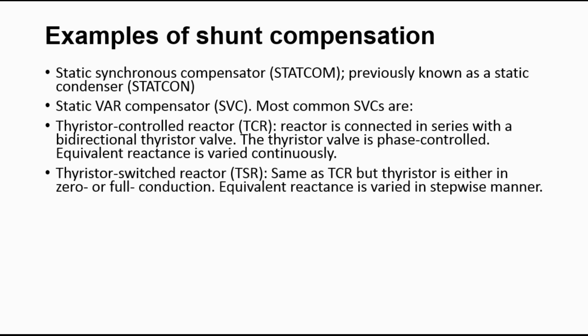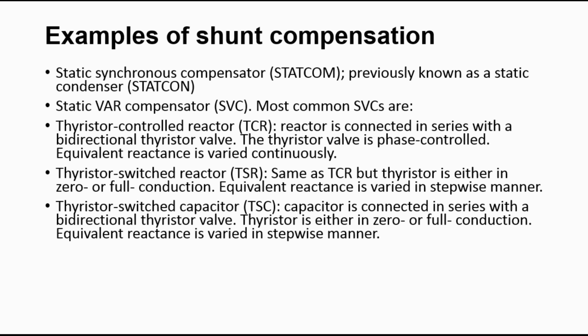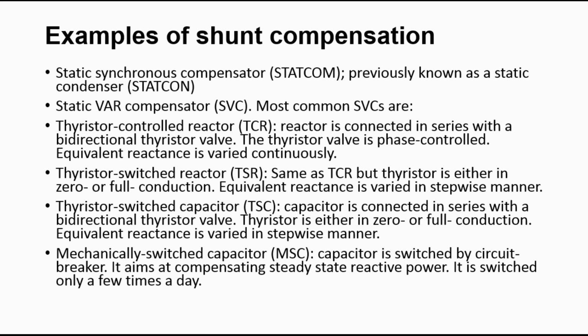Thyristor-switched reactor, TSR, same as TCR but the thyristor is either in zero, or full, conduction. Equivalent reactance is varied in stepwise manner. Thyristor-switched capacitor, TSC, the capacitor is connected in series with a bidirectional thyristor valve. The thyristor is either in zero, or full, conduction. Equivalent reactance is varied in stepwise manner.